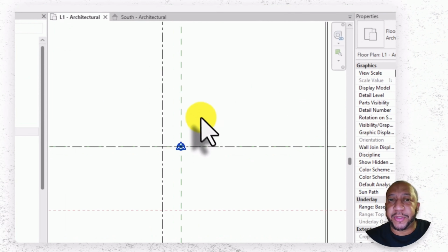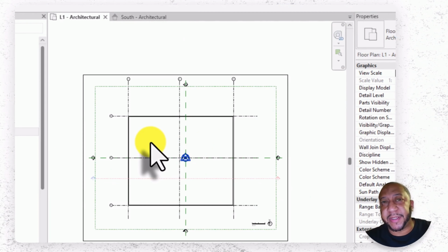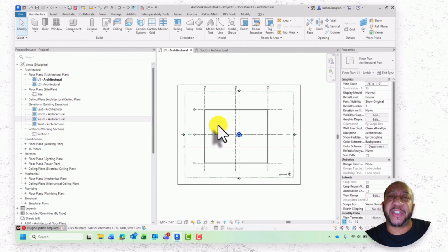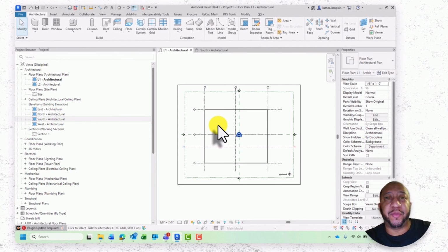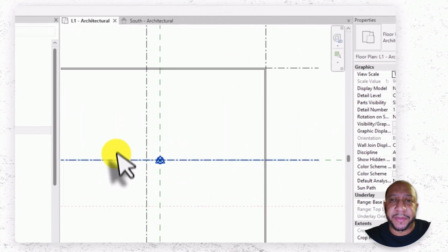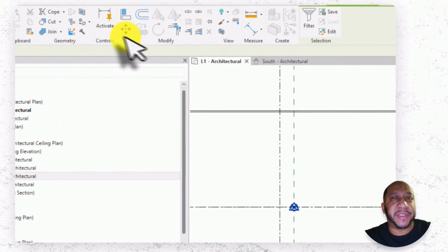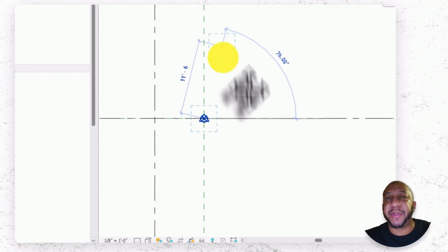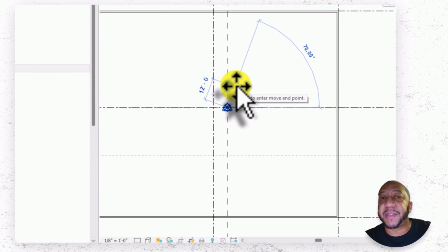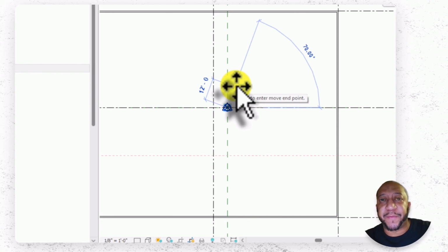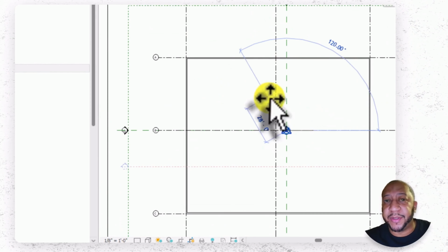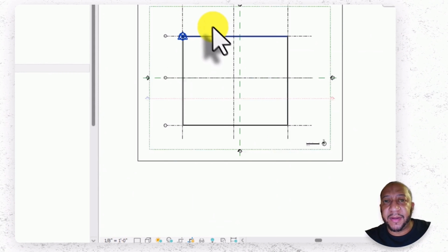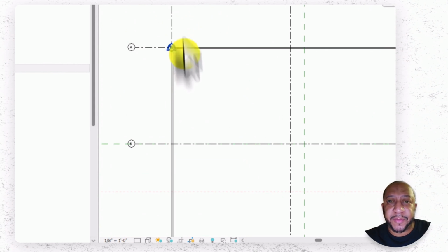So what we are going to do to move it, I'm going to show you a tactic, because you can't just move it right away. You've got to make sure that you unclip it first, because if you move it right away, I'm going to show you what happens. Let's say I want to move this to where I want it. Anytime you're going to move something, guys, especially if you don't have any survey information, you move to A1. So right now I'm going to move to A1, and I want you to see what happens when I click on this information right here.